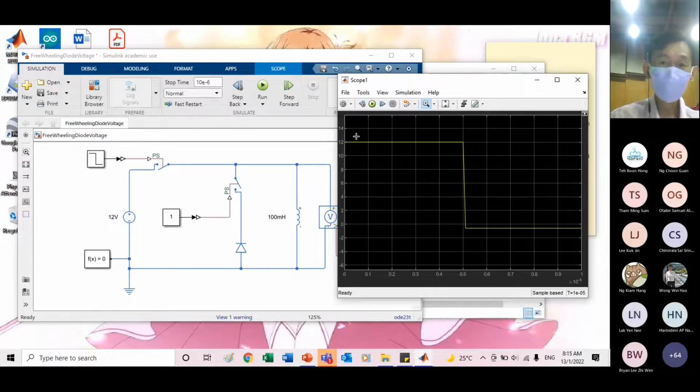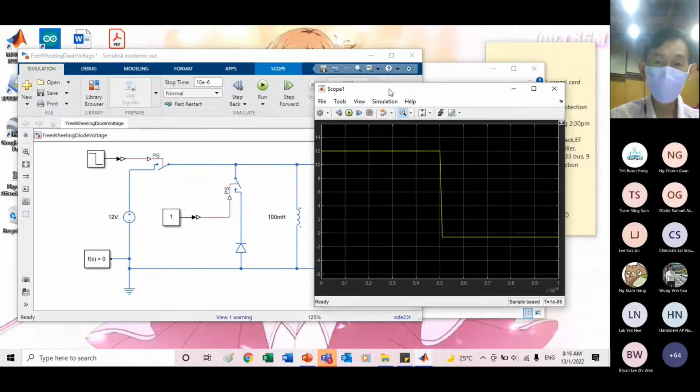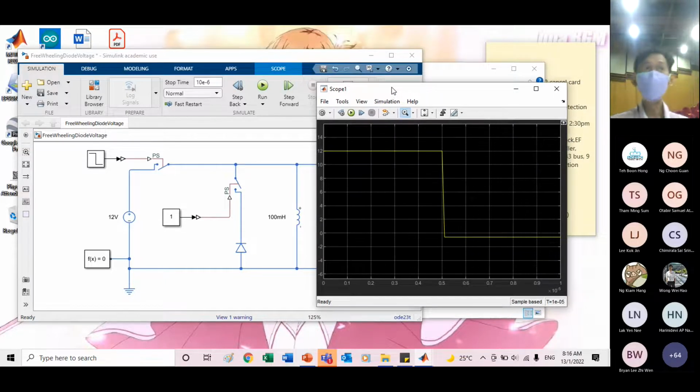So like I mentioned before, it is very important, especially for those involved in mechatronics, controlling motors. And when you use a controller chip, look carefully. If you are not sure whether the chip you are using has a built-in diode or not, then put an external diode. Even with the built-in diode, you have to check your motor current rating.